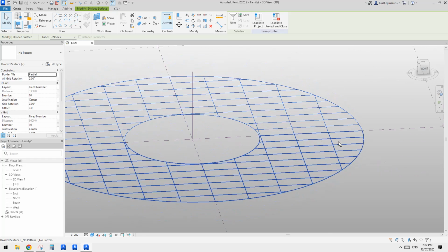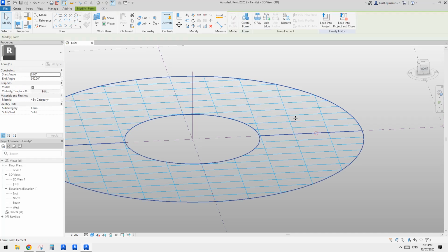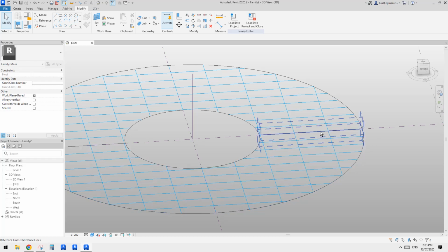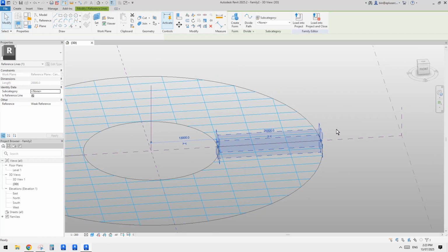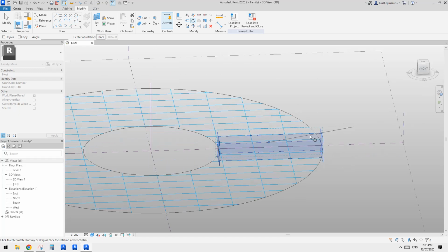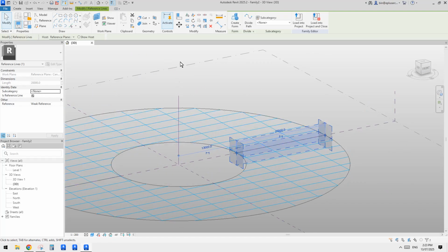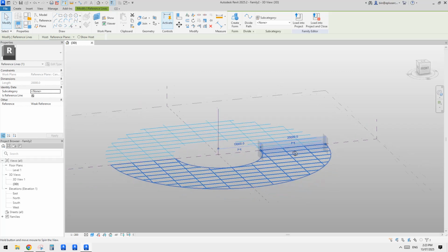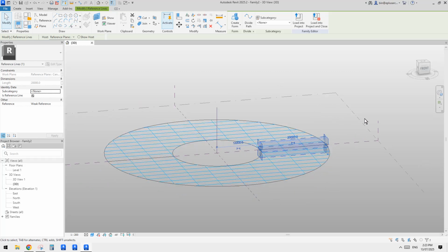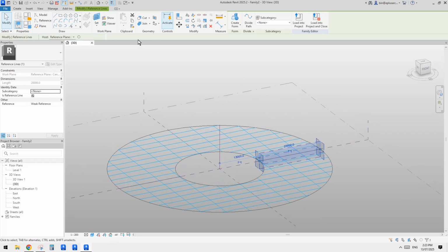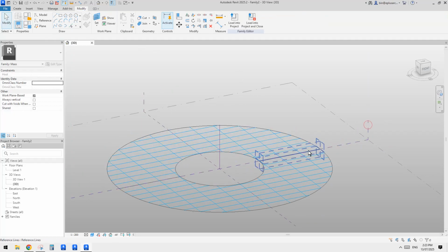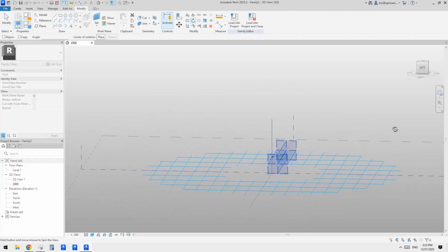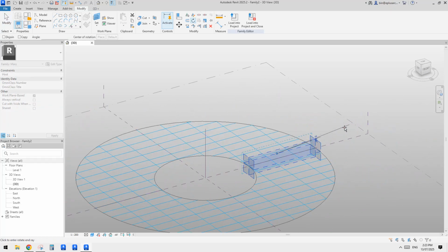So what we need to do is we just need to make this surface not flat. Okay, not flat. So to achieve that, we can just easily rotate this profile. Okay, hang on. Let me just try to pick the vertical, because I want to rotate this one on the vertical plane. Okay, so let's set work plane onto this and then try to select it all again. Yeah, I think that should be fine. Okay, I'll just rotate it by 0.1 degree.